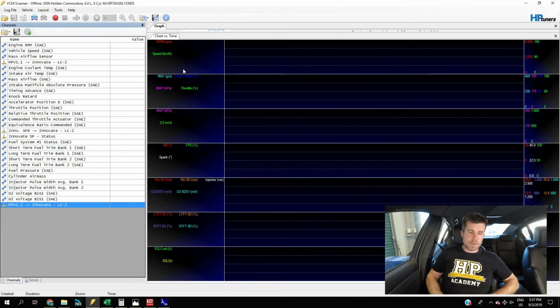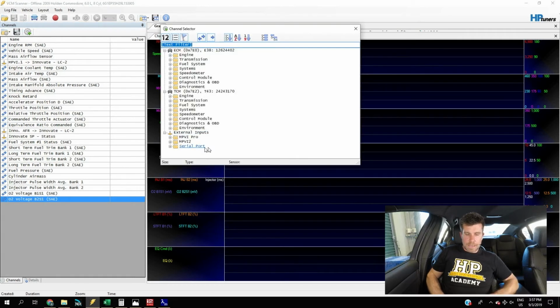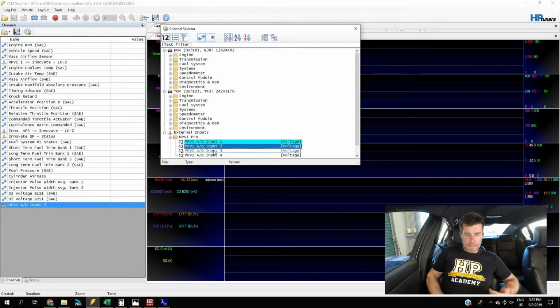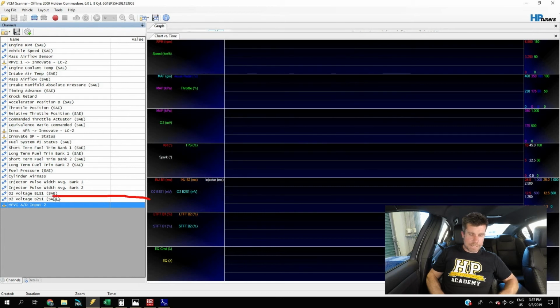And then we're going to head across to our scanner. We're going to bring that input in just purely as a voltage. So if we pretend that we are on the analog to digital 2, we'll click on that and bring that in. That now is just a raw voltage. When we start scanning, obviously I've got nothing connected, but if we started scanning, that's going to show us a voltage. It should be 0.5 volts, but more often than not, it's not going to be.